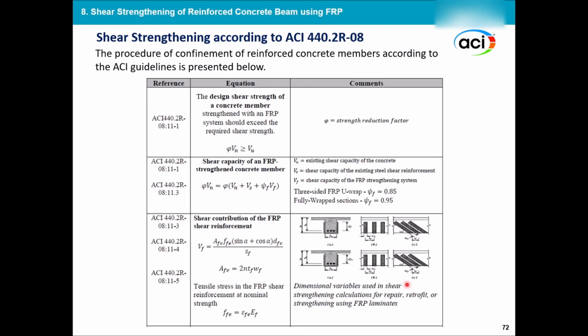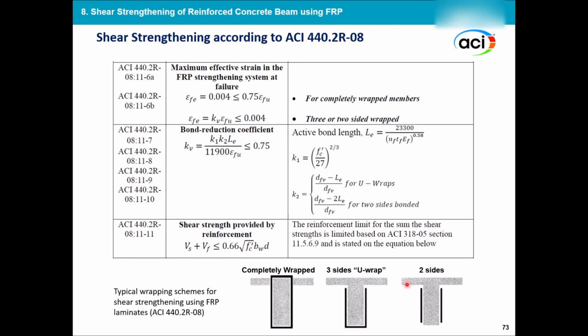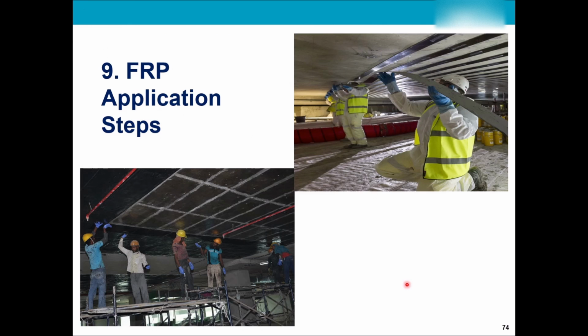And you can see that, having the MED and VED, which are applied from your analysis, how you can simply calculate the MRD, which is the flexural capacity of your section with the FRP, and VRD, which is the shear resistance of your section. If these two are bigger than the applied ones, voila, you have done your proper design. So please refer to Moodle and you will see it. Again, ACI as well, if you see, it's a little bit more complex, but follows exactly the same concepts.